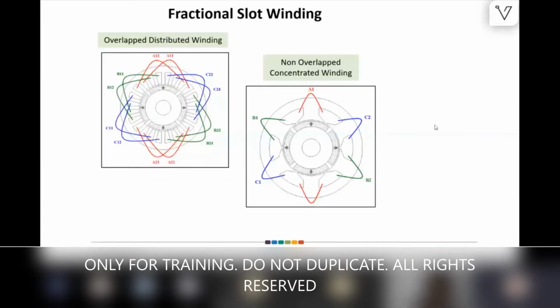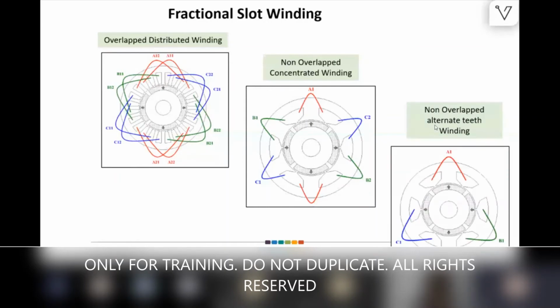There are many other windings. These are fault safe, fail safe, because there are many times we need fail safe. When the vehicle fails, if at least two phases are available, and if there is less mutual inductance between the two windings, or three windings, then we can have at least two windings and some torque to push the vehicle or take it aside, or pull aside somewhere in a safe area.